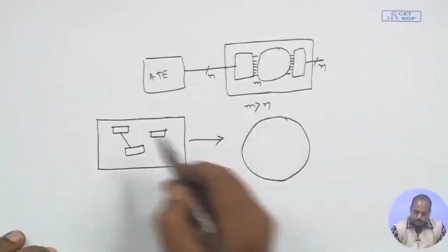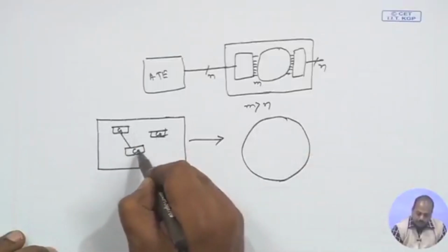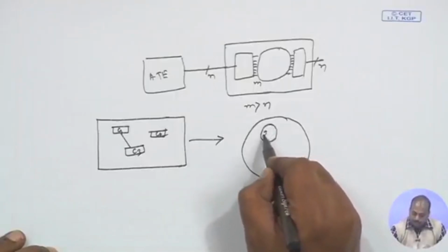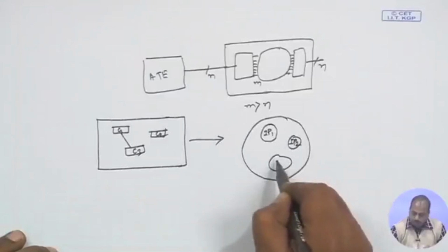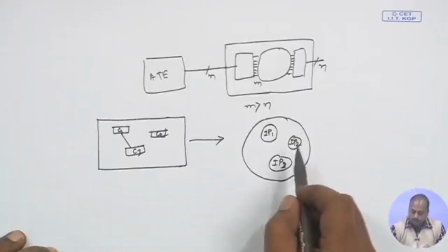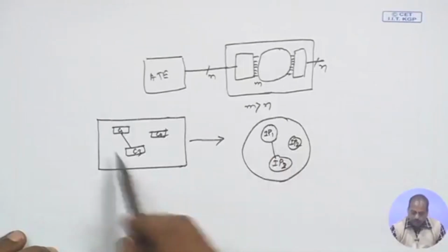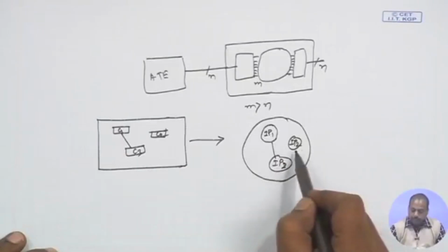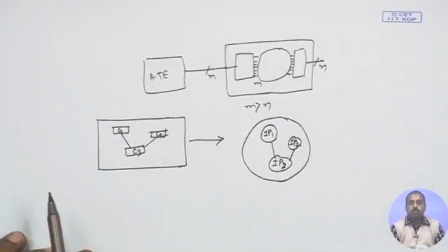So, all these chips, say C1, C2 and C3. Now, I get the corresponding IPs from the vendors: IP1, IP2 and IP3. They are fabricated on this silicon wafer, and then the connections between them. Here I have a connection from C1 to C3, here IP1 to IP3. There may be another connection from IP2 to IP3, where there was a board level connection from C2 to C3.